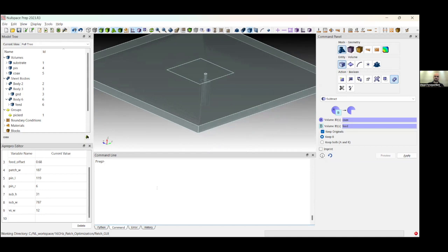For the same reason that we mentioned, for the mesher to know if there is an overlap, we need to imprint all the volumes and merge them together so that the mesher knows that there's no conflict on the curves or surfaces or volumes.